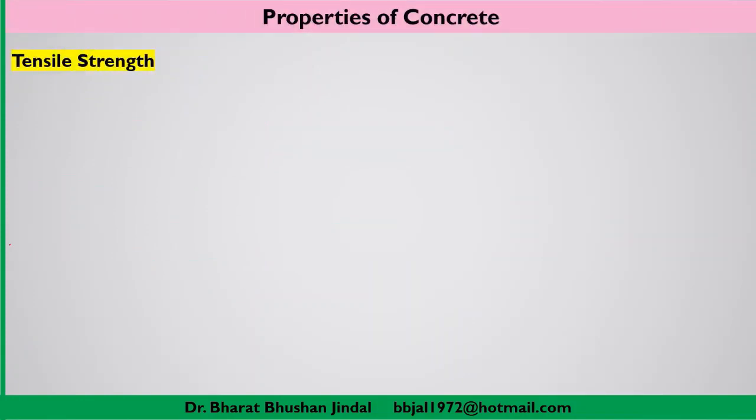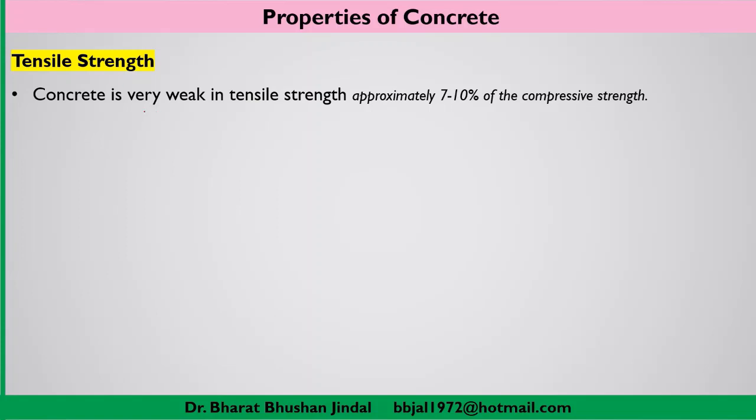Now another important property of concrete is tensile strength. We know that concrete is very good in compressive strength and has poor tensile strength. So that is, concrete is very weak in tensile strength, approximately 7 to 10% of the compressive strength.